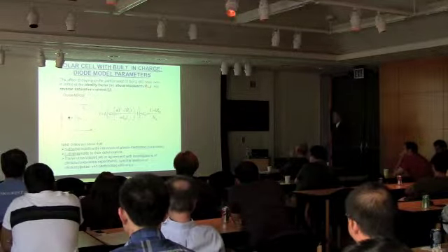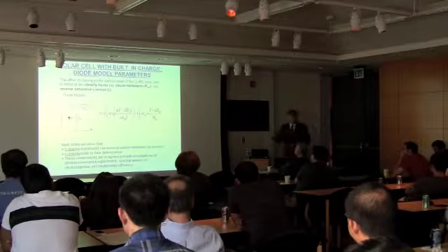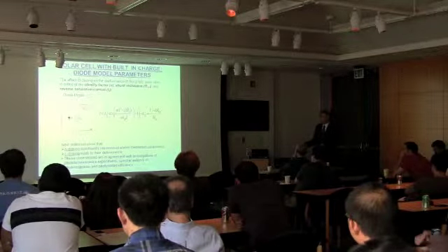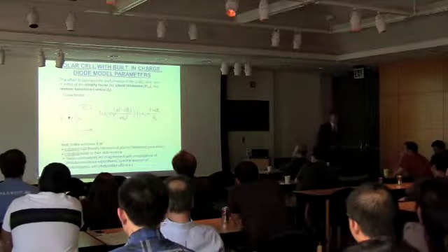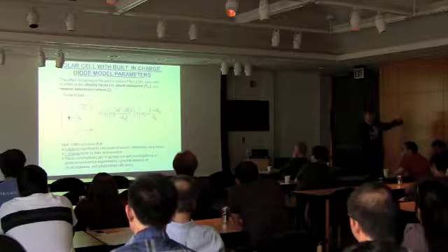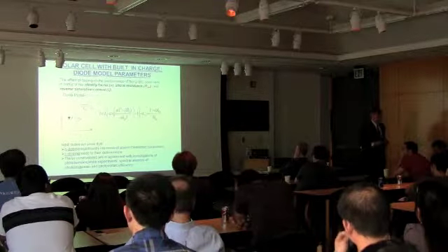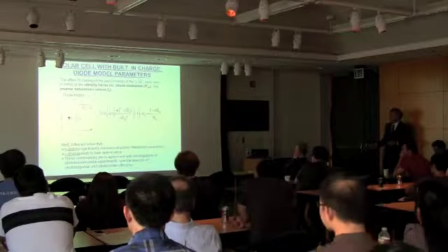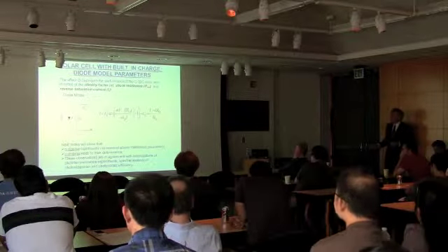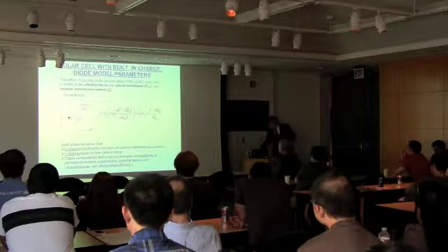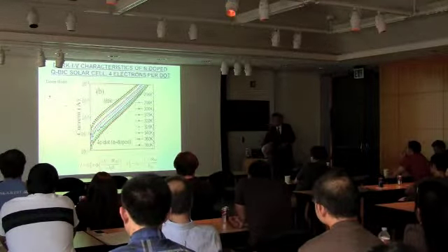What is important here is that for reverse bias voltage, the current will be the so-called saturation current, and this demonstrates the quality of the junction, because reverse current is controlled by recombination inside the intrinsic region. And the so-called non-ideality factor is introduced here in the place where the current increases exponentially for the forward bias.